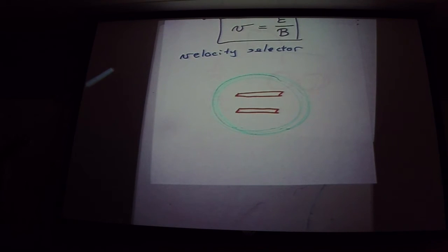My heart is too fast for it. Your heart won't fibrillate because of that. But if you've got something at a lower frequency, enough that your heart gets mixed up, it's a problem. So higher frequency, lower current, less danger.